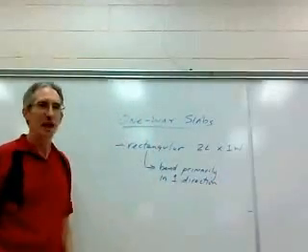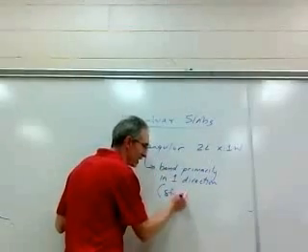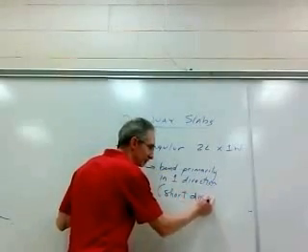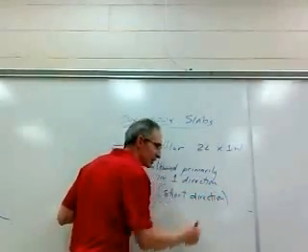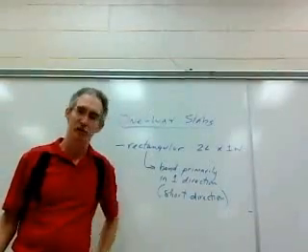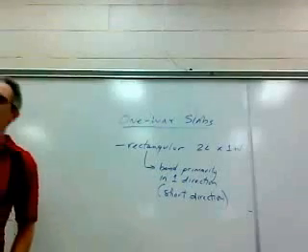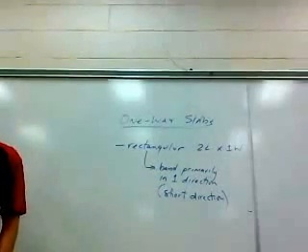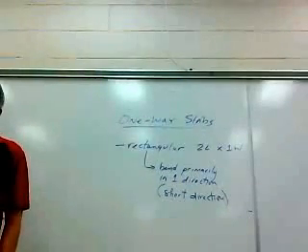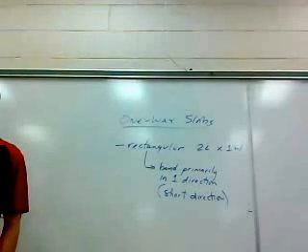And since they bend in one direction, that direction, I should tell you, is the short direction. Since they carry moment, or they bend primarily in this one direction, the short direction, the reason we lump them in right here, with our discussion now, is they behave exactly like rectangular beams.